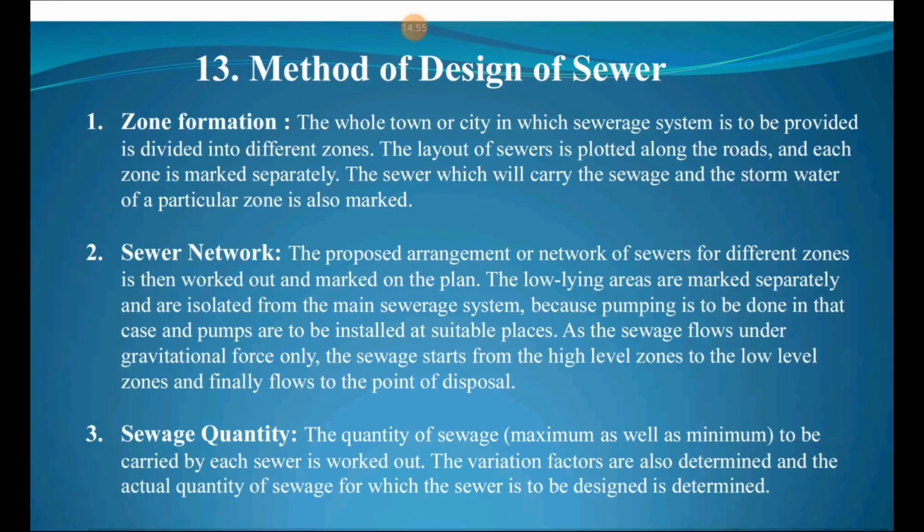Then we are going to discuss the method of design of sewer that are important. First step is zone formation. As discussed earlier, the whole town or city in which sewerage system is to be provided is divided into different zones. The layout of the sewers is plotted along the roads and each zone is marked separately. The sewer which will carry the sewage and the storm water of the particular zone is also marked.